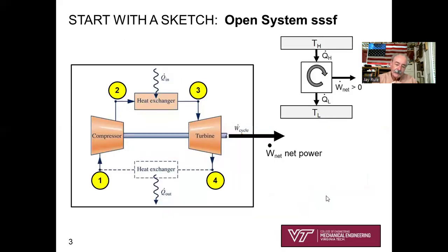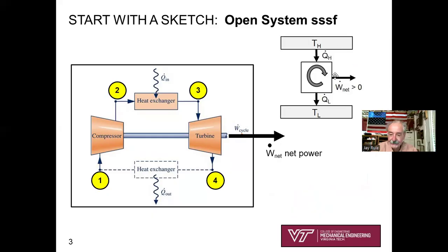And so now here's our thermodynamic model for our Brayton cycle. So remember, in the back of your mind, here's our schematic of any system operating in a cycle steadily in time. We've got a high temperature heat source. Well, that's going to correspond to this heat exchanger here. We've got Q dot H to the heat exchanger. This black box is the equipment associated with the gas turbine engine, the compressor connected by a shaft with the turbine, and net output power coming out.